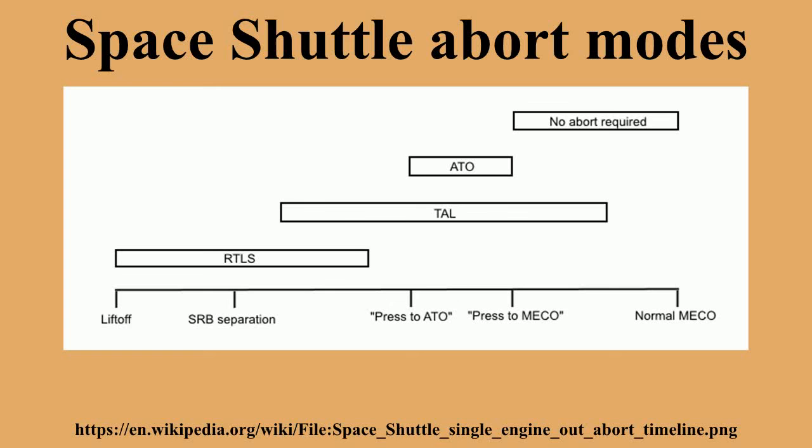into a contingency." The Soviet shuttle Buran was planned to be fitted with the crew emergency escape system, which would have included K-36RB seats and the Strizh full-pressure suit qualified for altitudes up to 30,000 meters and speeds up to Mach 3. Buran flew only once in fully automated mode without a crew, thus the seats were never installed and were never tested in real human spaceflight.